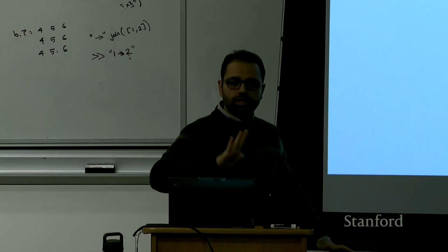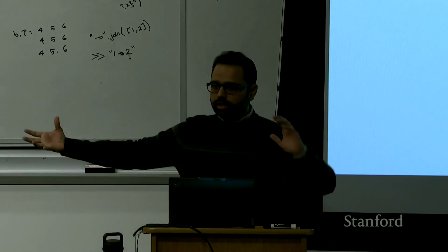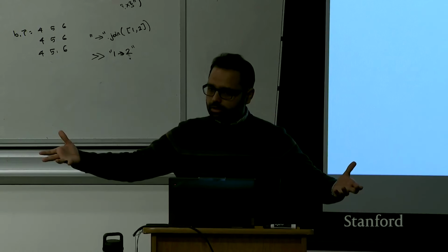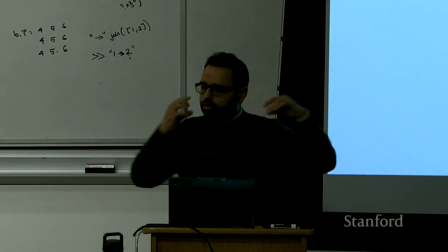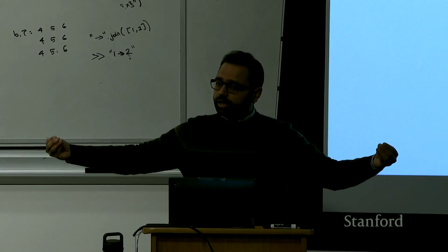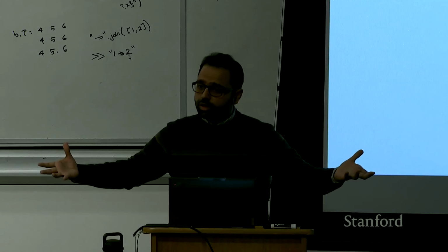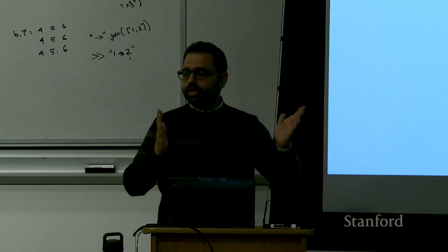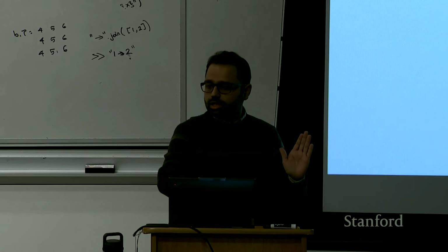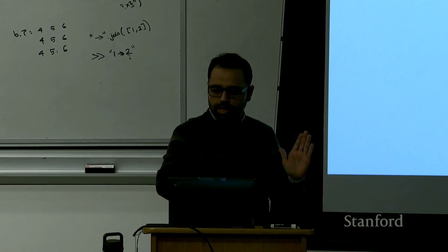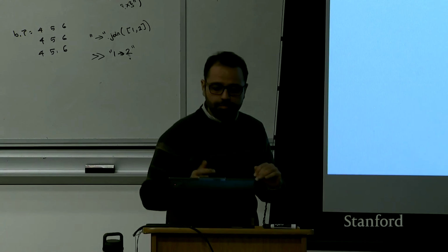So the motion planning problem is defined by robot start, goal, and environment perception. Right? Standard motion planning problem, you give it to a classical method or optimizer, it takes the start and goal and your environment, like distance to obstacle or whatever observation you have available. So that defines the problem. And in this case, we are giving only this problem set. So QS and QG and environment perception go through the neural network and you predict this T.